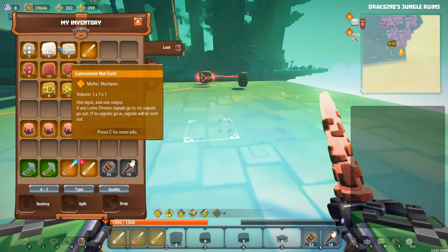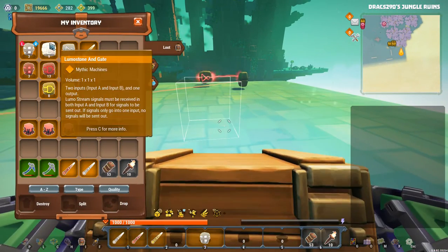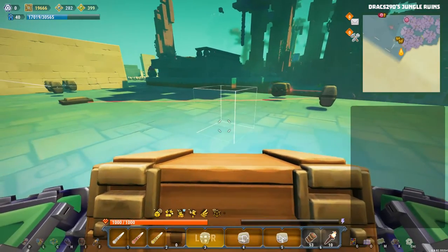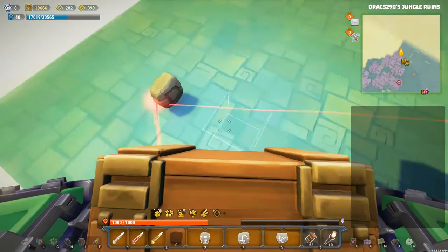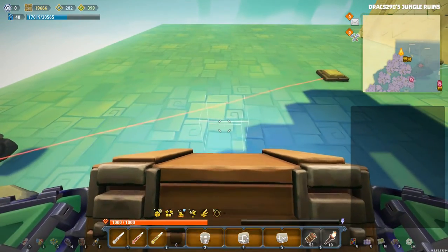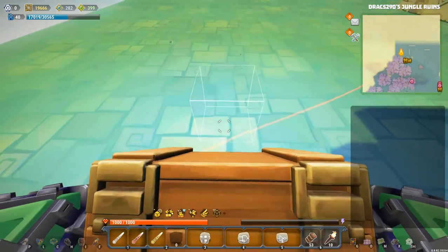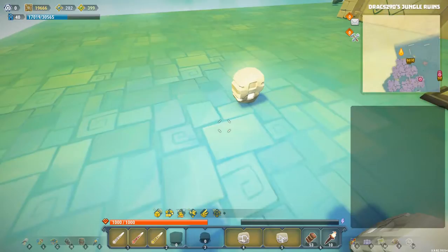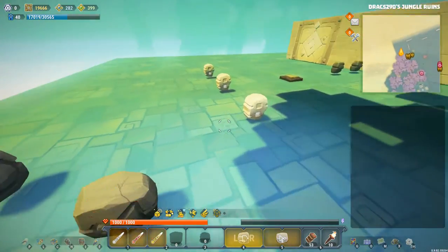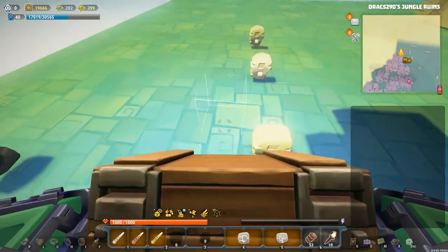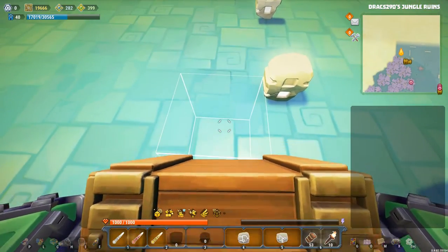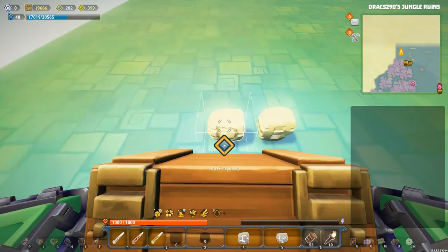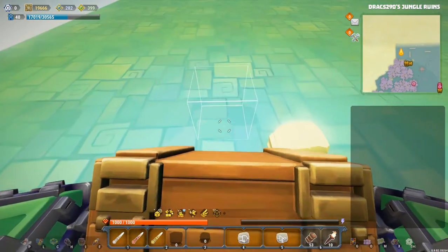Now the next thing we're going to do is go through and do the actual counter. The counter is pretty simple and straightforward. We've done these before. That's okay, we'll still go through and do this on camera. So first of all, we're going to place down our latches. That is the correct way, yes. We're going to place our latches down with a little bit of a gap between each one, just like that. And then we're going to place 2 AND gates for each latch, 1 and 2, 1 and 2, and 1. Oops, that's not where I wanted that one. It's going to go here and there.